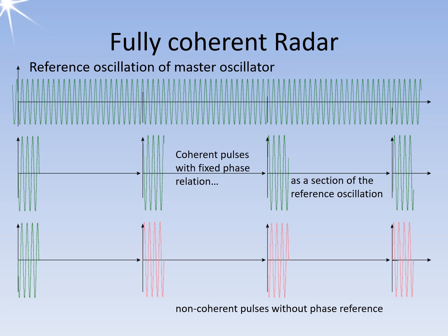Solid-state transmitters are almost always fully coherent. Also, some vacuum tubes can produce coherent signals when used as amplifiers. Mostly traveling wave tubes or klystrons are used for this purpose. Only a short section of the constant oscillation of the low-power oscillator is ever cut out, amplified, and transmitted.